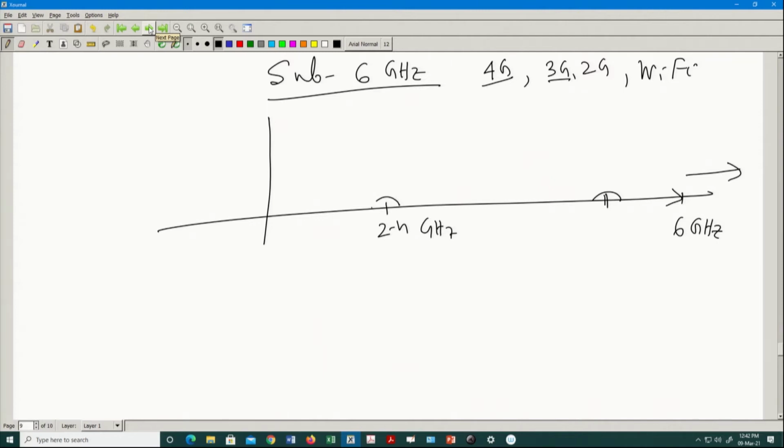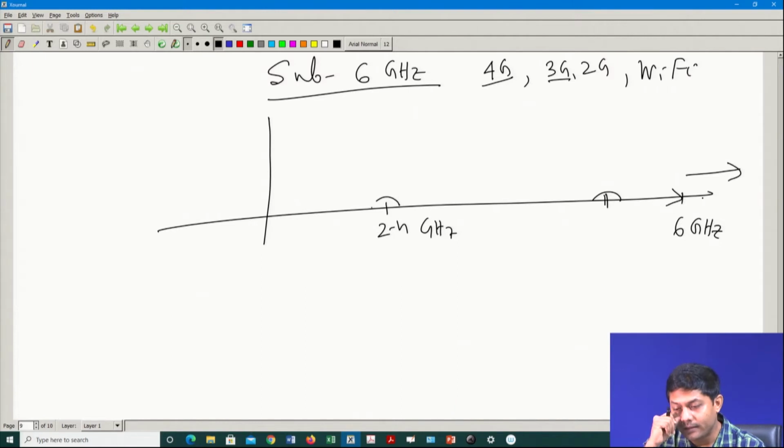So, here we are talking about why to increase our RF while we have predominantly 6 gigahertz, or at least say 7, 8, 9, 10 gigahertz also available. The issue here is that though they may be available, it is not so much available compared to what I need, okay, because your data rate might be very high. You may support 1 Gbps data rate, such a very high data rate, and 100 megahertz or 20 megahertz bandwidth is not good enough. Okay, this is one part of the story.